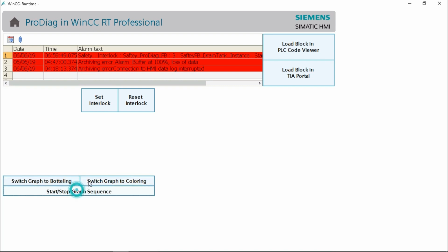You just see, okay, there's a failure coming up, something is wrong in the machine. Same thing for the graph overview, okay? You place that maybe on top of the screen or somewhere on the screen, but it's just additional information that you see an error is coming up right away. So the next thing you would do is use the button which you can display in the control itself in order to jump to the alarm view control, which is in another screen, in your actual diagnose screen.